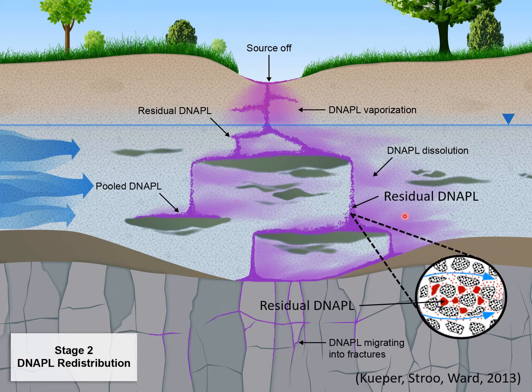It's this particular distribution, which we call the DNAPL source zone, that we are striving to accurately characterize and then monitor during remedial activities. And this leads to the motivation of geophysical techniques, which can provide cost-effective, non-invasive, rapid, and continuous information in both space and time.